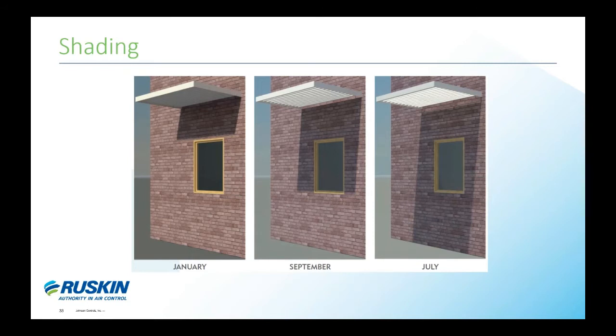Here's what sunshades will look like throughout the year. This shows you don't need moving parts to have a truly efficient sunshade. The pictures show that you can have the sun allowed in your building during the cold days of the winter, as you see in the January part of the slide, and have it shaded in the summer with the effective sunshades, where you have your September and your March as being your swap seasons.